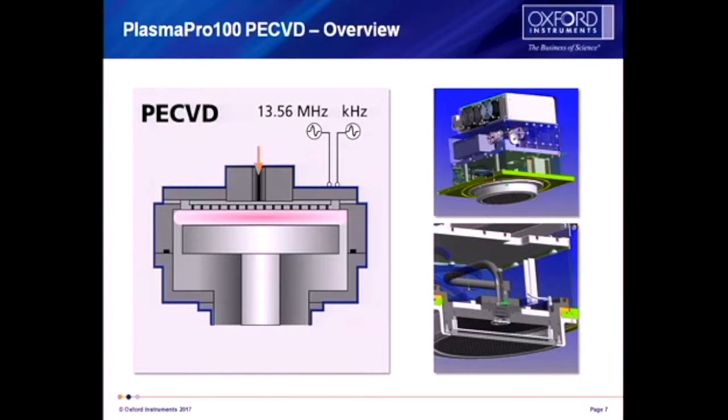So the other important feature when it comes to plasma production is a fast-matching auto-match unit. This is really, really important because if your auto-match unit doesn't match the impedance of the plasma, you get a lot of reflected power back into your generator, which is, one, not very good to the generator, and it also means that the power you're asking for in the software isn't being delivered to your plasma. So by having a really quick auto-match unit, you're taking out a lot of the uncertainty in the process, so it's much more repeatable.